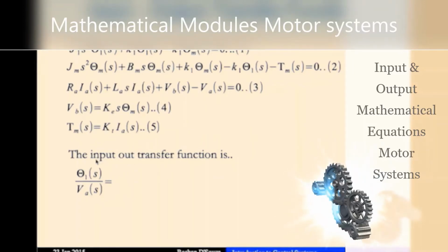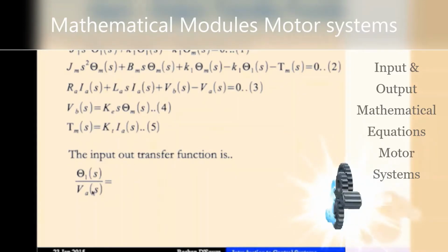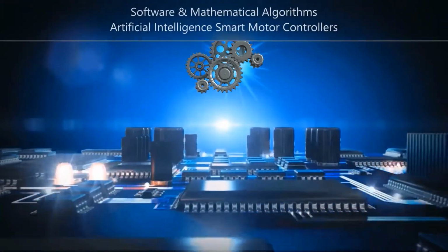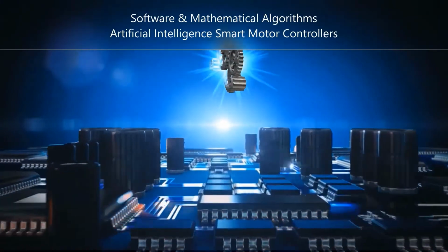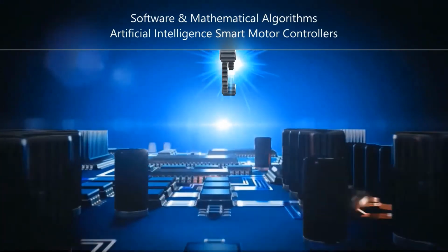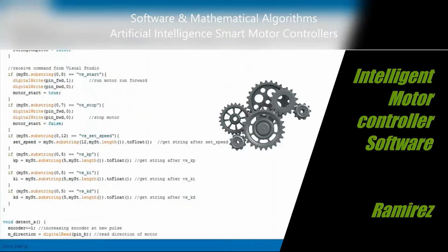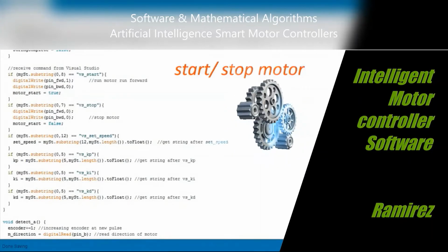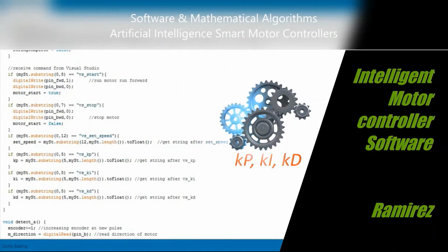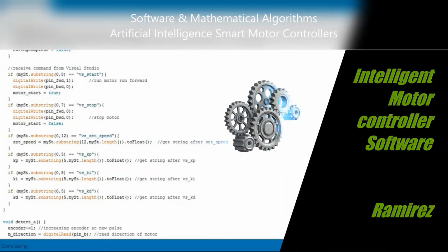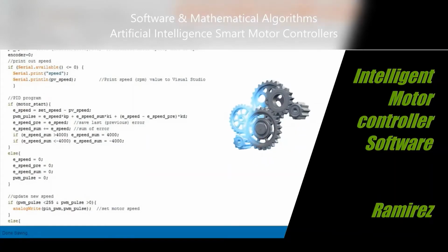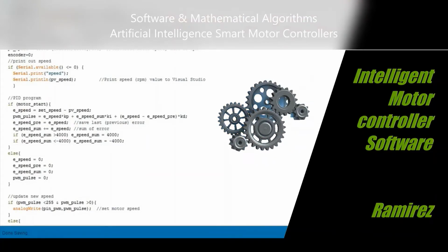A pulse width modulation (PWM) signal is a method for generating an analog signal using a digital source. A pulse width modulation signal consists of two main components that define its behavior: a duty cycle and frequency.